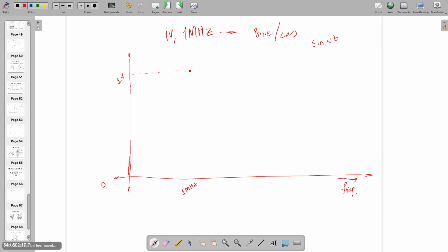But I want to draw this one where I'll convert this 1 volt to dB, which will become 0 dB, and I'll convert 0 to dB. So tell me, what will be the 0? It will be from the 0 dB line to the negative. Where? 0. I need 0. So 0 is possible in logarithmic scale? No. So there has to be some number. That number I already told. Let's keep it minus 300 dB, which is by Cadence, which is 10 raised to minus 15. For the case of MATLAB, maybe minus 600 dB.